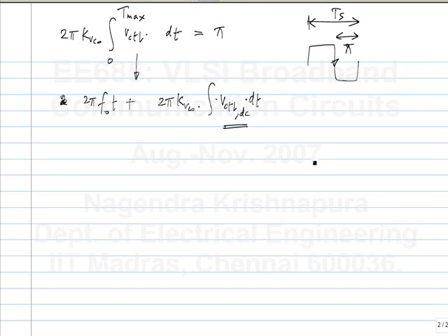So this V control DC is what I call the DC value to get the right frequency. Okay, maybe you are not operating at the free running frequency, you are operating at some other frequency, then you need to apply a DC to this. Now, if this is all there is, then the VCO frequency is exact. The VCO frequency is f naught plus k VCO times V control DC.